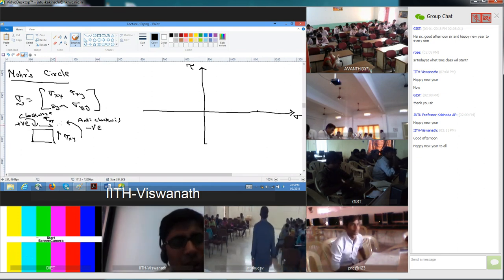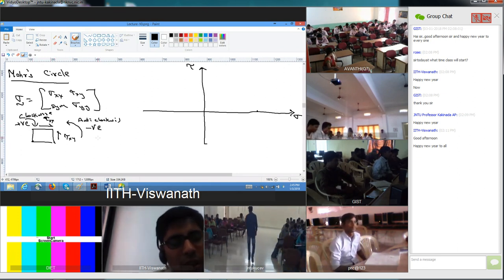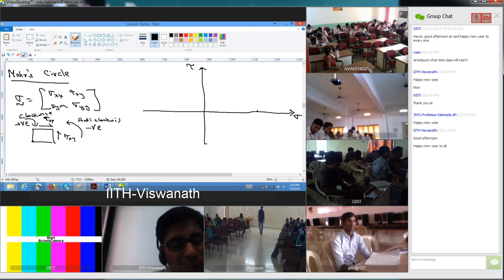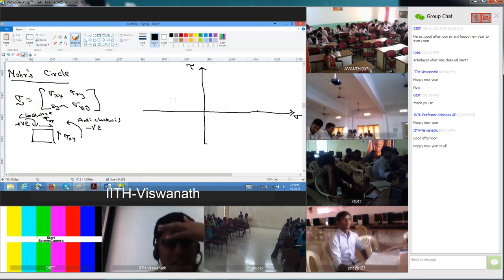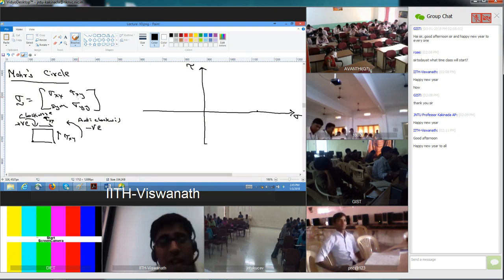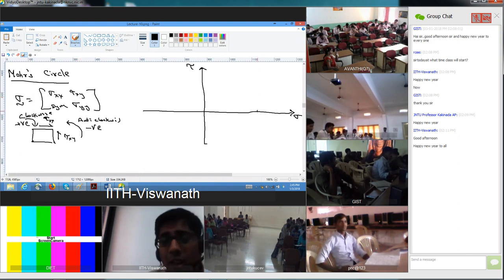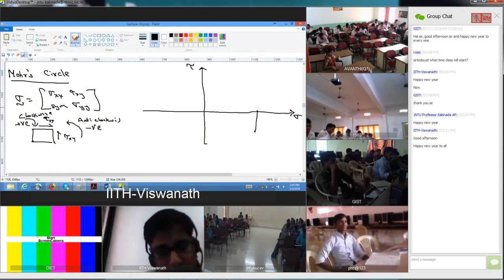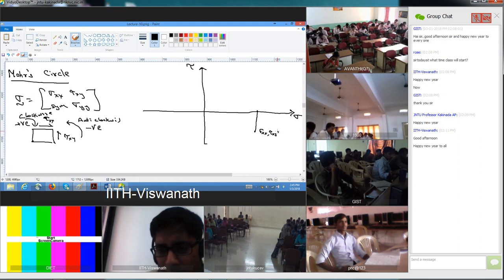The same shear stress would give you positive. So this is my notation. I mean, if you want to reverse it, you can reverse it, but be consistent all throughout. But in this course, we will try to use this as our notation. So any shear stress that gives you an anti-clockwise will be considered a negative shear stress, and any shear stress that gives you clockwise will be positive. Now you take this one. Let's assume that this is giving a negative shear stress in this axis, and this is your sigma xx. So this point is sigma xx comma tau xy.